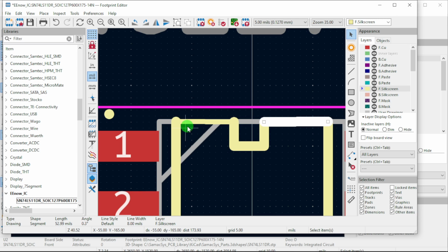It says warning. So 31.5 is my minimum. So let's do 31.5. If I make 31, alright, let's make it 32. That's not the minimum, so it's 32. So now let's run DRC. The warning should go away. Yeah. Okay, and everything is related to the board.